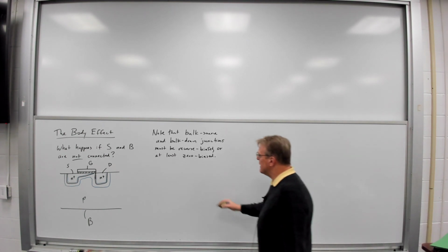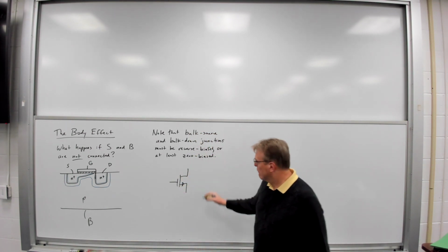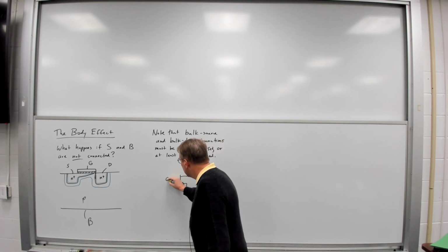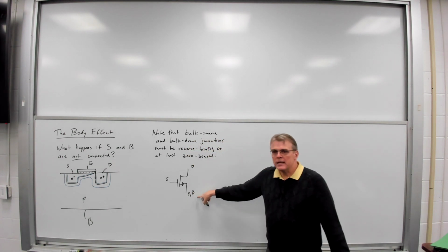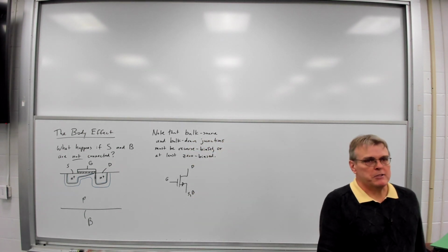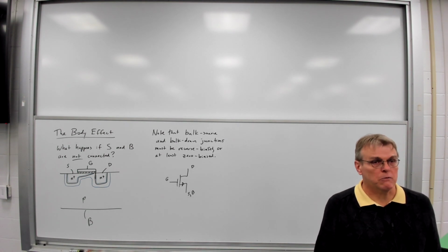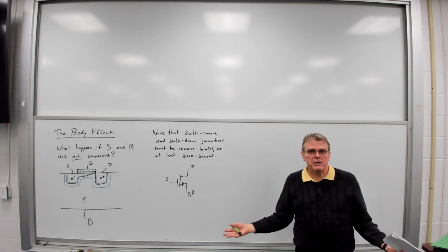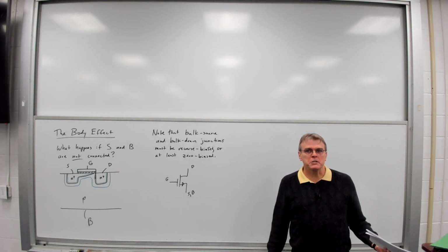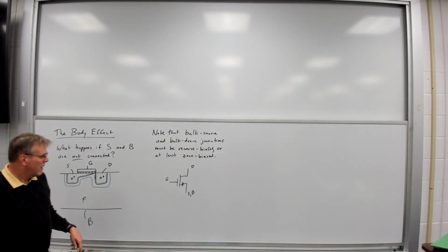When we were looking at our three-terminal MOSFET before, we always had drain, gate, and we said source and bulk are connected together. So in this case, we're assuming a zero bias. The voltage across that source-bulk junction is zero, which is off. That is, we basically treat anything less than or equal to 0 volts as reverse bias. So at the very least, we need to be this.